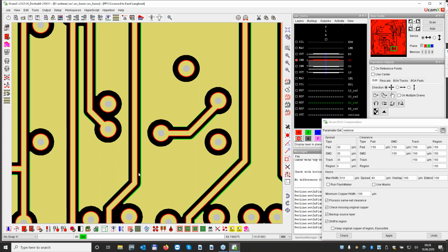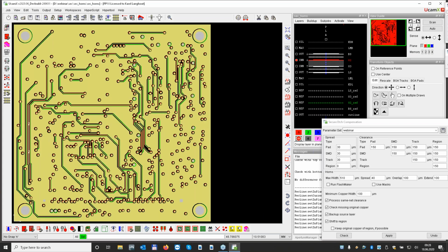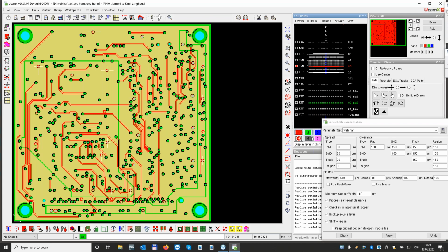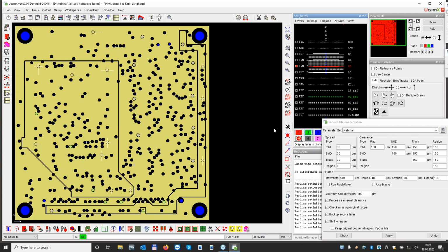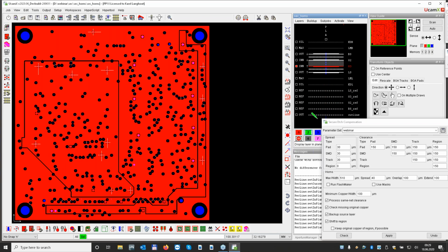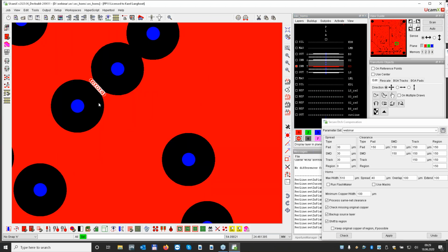It also takes care that if we don't have enough space, now I need to see, because I think there was still something that I missed on this layer. I now remember, it has to do with the fact that if I do it like this, you can see it much better. If I look over here, you can also see we don't have enough copper here. So also this will be fixed, these kind of situations.